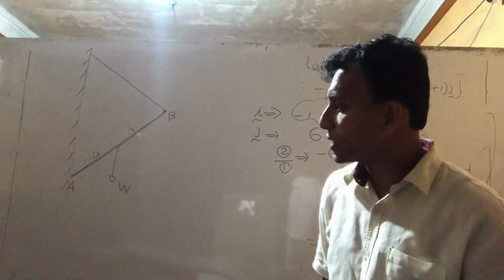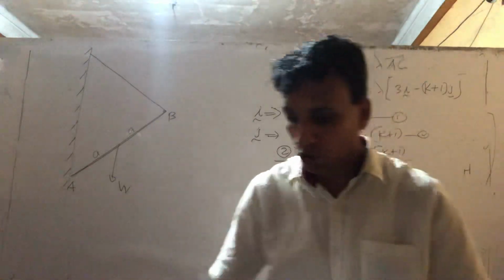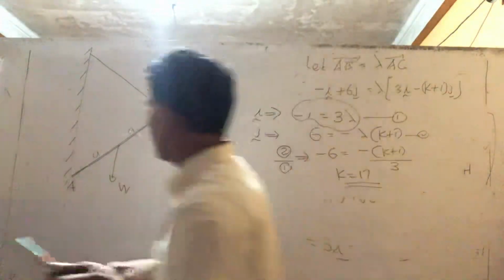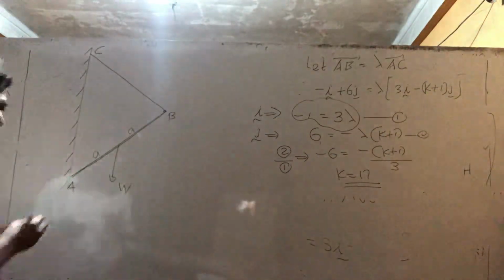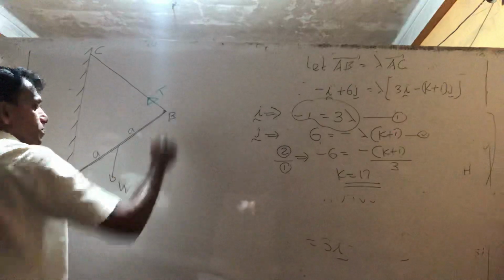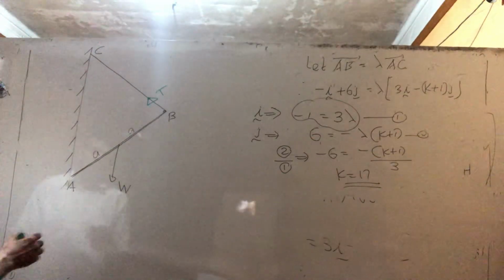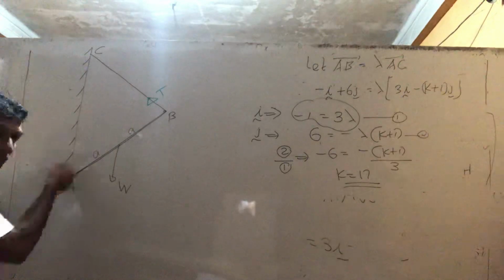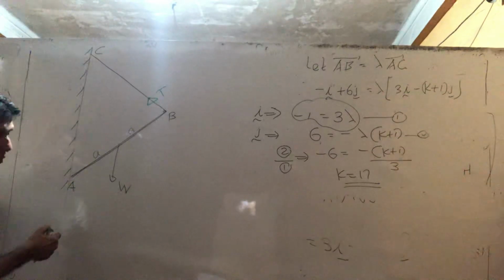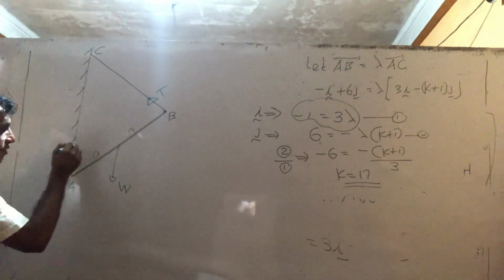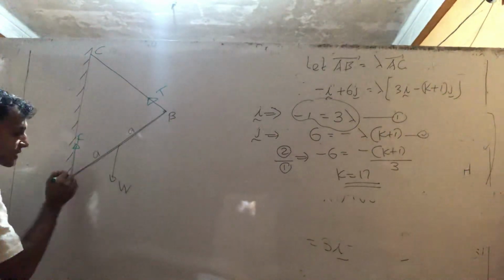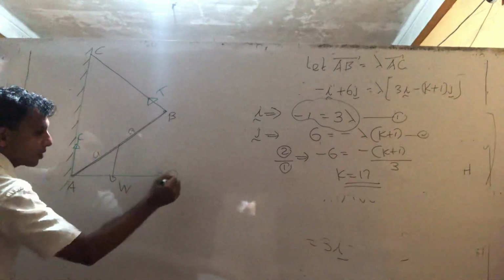And what are the forces acting here? The force diagram is important. The string: here they mention point C. So this is tension T. And what happens here? The rod will slip downward. The rod slips down because of friction on the rough wall. Therefore friction F opposes. And the reaction exerted by the wall is the perpendicular reaction.